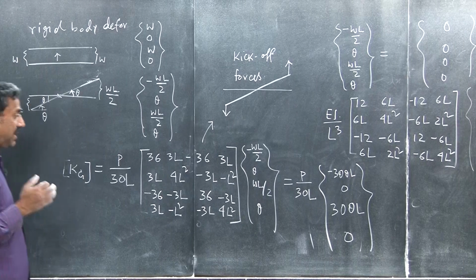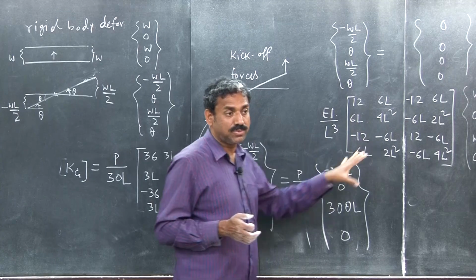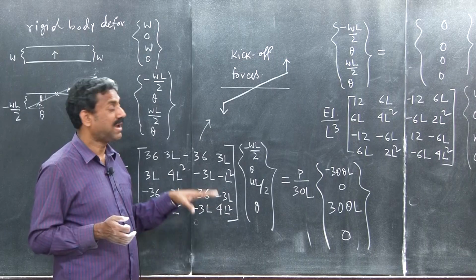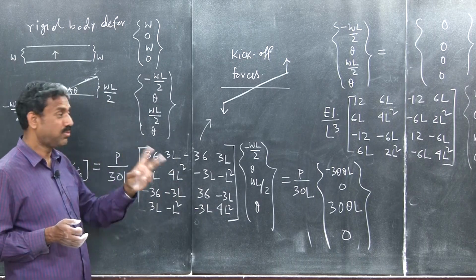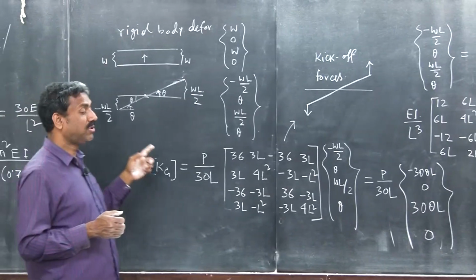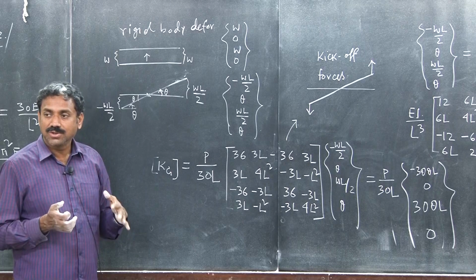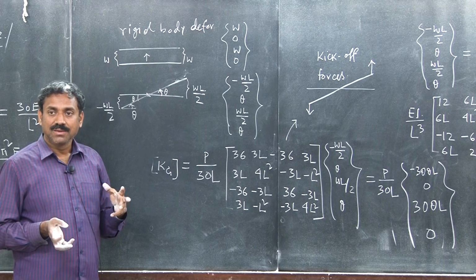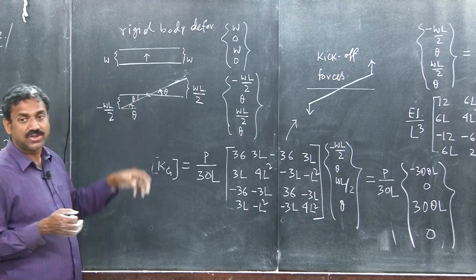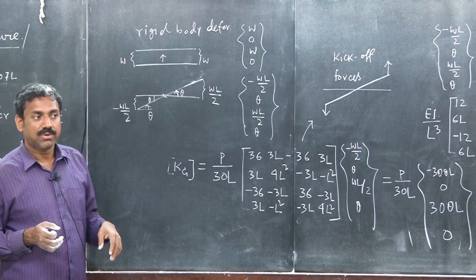So, the takeaway is that unlike the elastic stiffness matrix, the geometric stiffness matrix does not preserve the rigid body modes. It does not show at least one rigid body mode. It should have two rigid body modes. One is shown, the pure translation part, but it is not showing for the pure rotation. Why? Because it is unable to distinguish between the von Karman nonlinear strain and the strain due to rigid rotation. Clear? Okay, thank you very much.